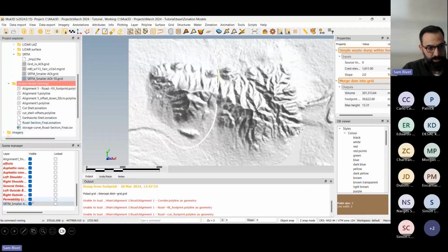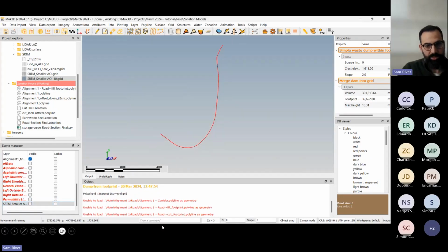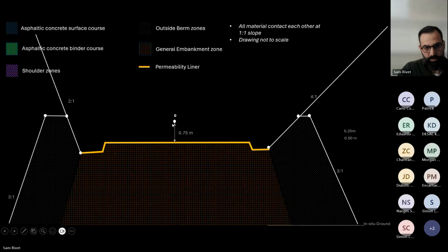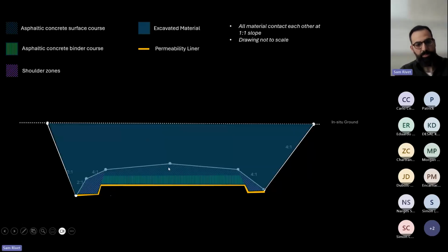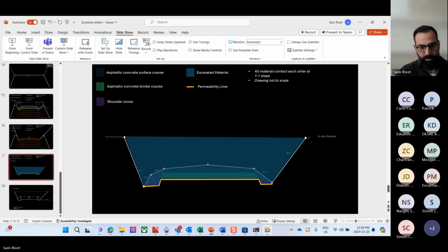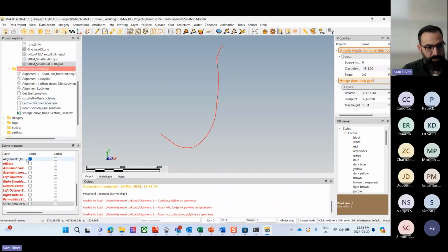what I do is, let's just close down some layers here. Okay, also, one thing to take into account, your final road alignment is going to be lower than this cut model. So you're going to just need to take your alignment, drop it a little, build this shell, modify your topographic surface, and then put that back in. I'll just show that to you now.